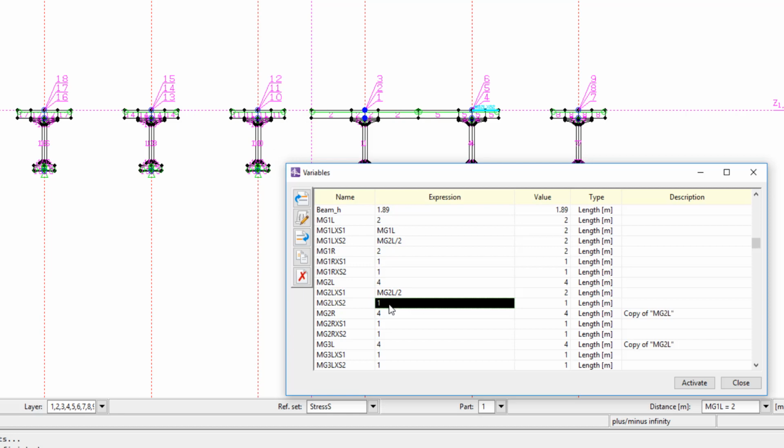When adding new composite beams, additional part elements are automatically introduced into the cross-section. That means that each composite beam will have its own individual part number. This is important after analysis to have the normal, split and joint forces in each deck's composite beam.